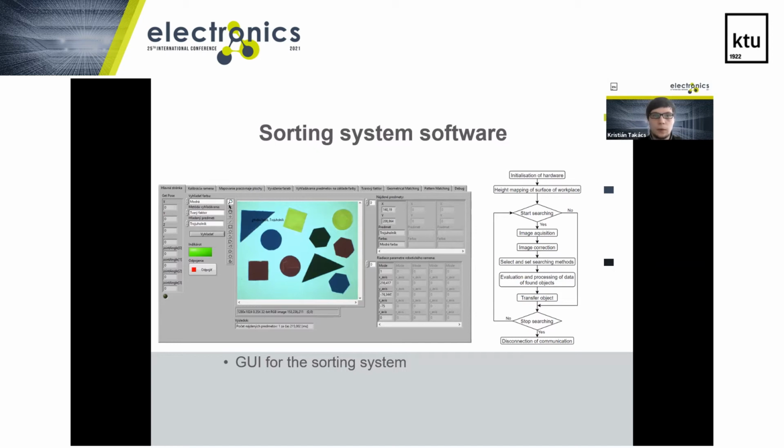If the algorithm does find a match, it calculates the center of mass of each matching object in the image. This value is in pixels, so the algorithm transforms the values to the corresponding form for the robotic arm, which picks up the found objects and puts them aside. As a last step, the endpoint of the robotic arm moves back to its home position, which does not interfere with the view of the camera.